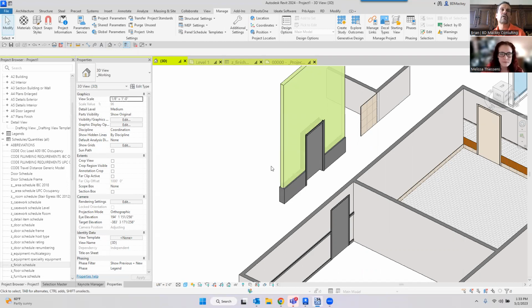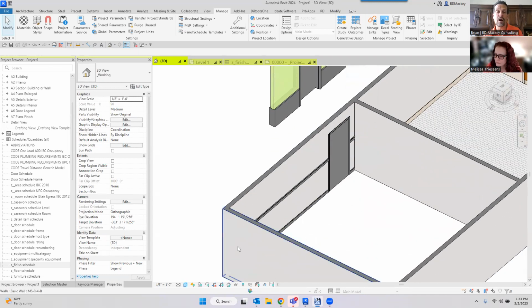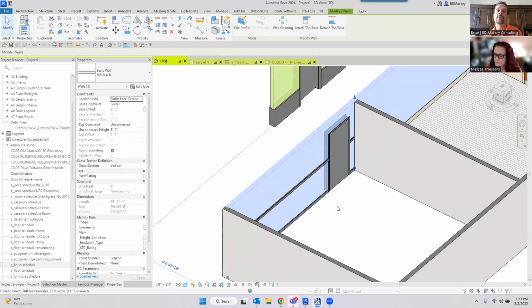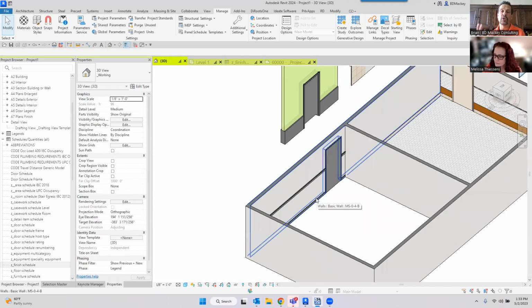The parts are the same. They originally introduced parts, and the only change that they've made, to my knowledge, is that you can part through a link. Desiree actually did a project when she was like two companies ago, a tilt-up concrete building or something, and she literally took the architect's concrete walls and created parts through the link. So if they updated the wall, her parts would update. And then she literally just said, hey, great, now I'm going to only display parts. These are all my concrete walls, etc. So she could do it. She could then manipulate the parts, etc.